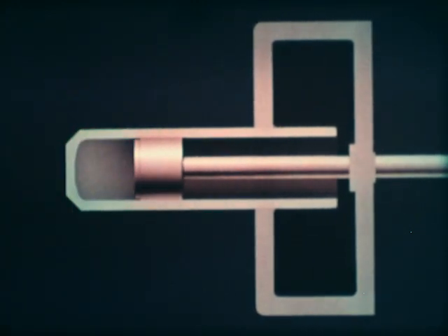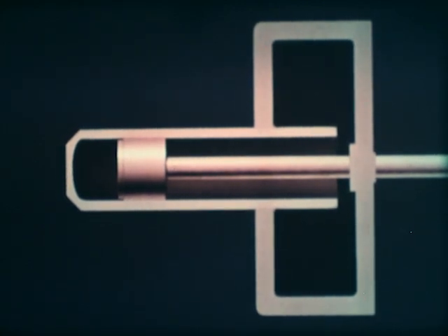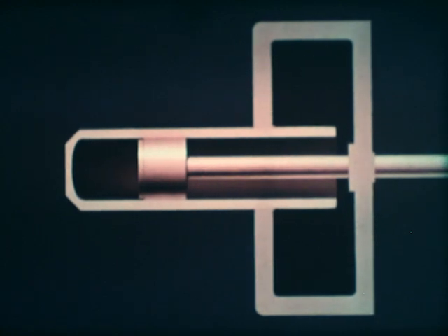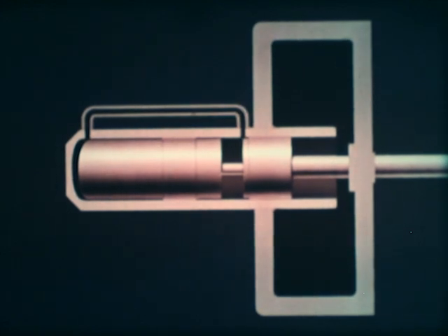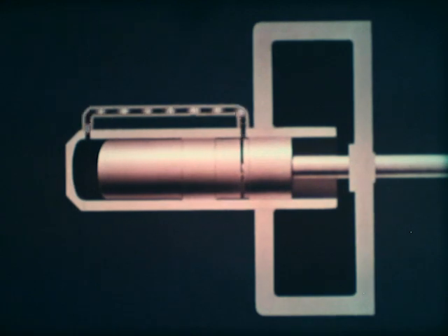Not only is the gas alternately heated and cooled, but also the cylinder wall. The heat spent in this way is wasted, but it cannot be neglected as the heat capacity of the cylinder wall is much higher than that of the gas. Robert Stirling solved this problem with the so-called displacer piston. This piston drives the gas from one end of the cylinder to the other, demanding hardly any energy as the pressure on both sides of the piston is almost equal.